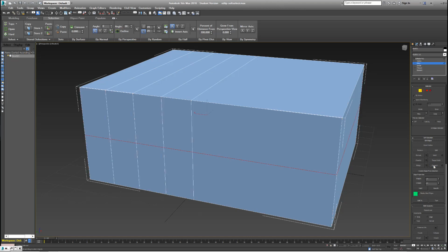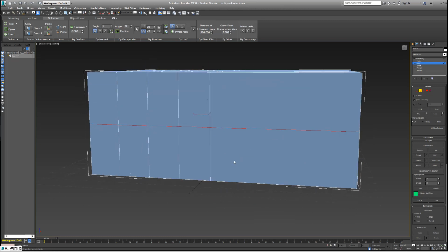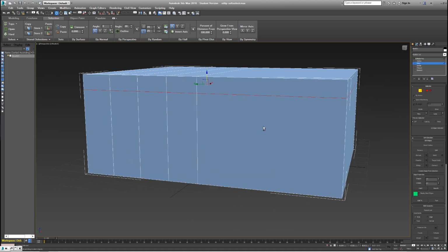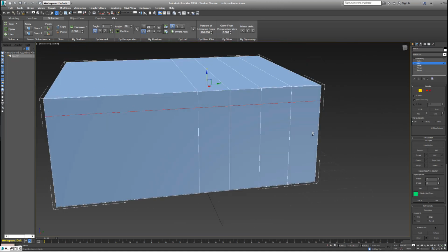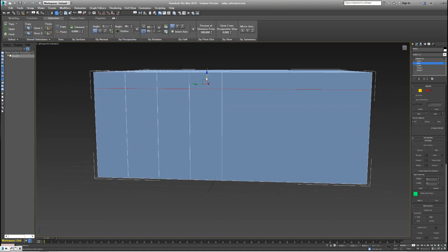connect to create a line along the opposite axis. And with that line, you can hit the W key. You can move that up along, so say the Z axis for here. Whoops. If you ever suddenly select another edge by accident, you can just hit loop, just like what I did, and it reselects that entire loop around your box.